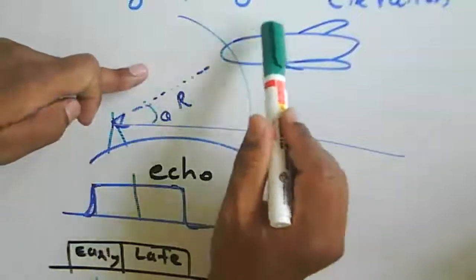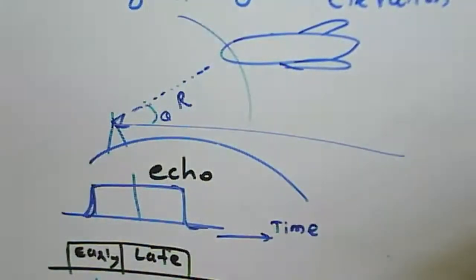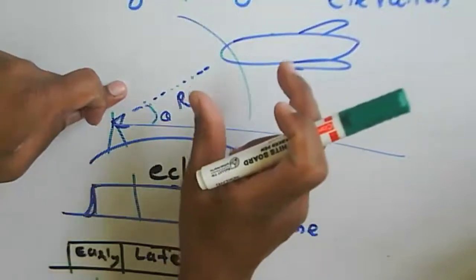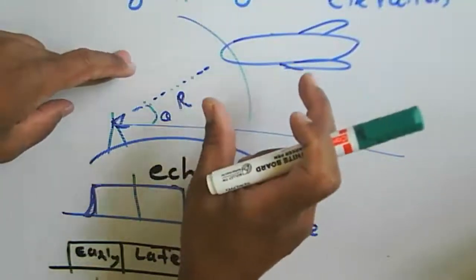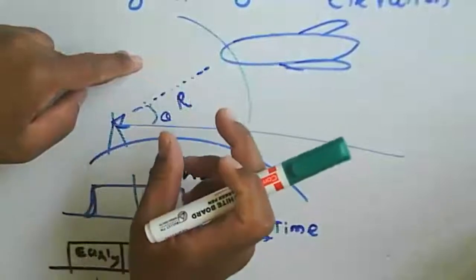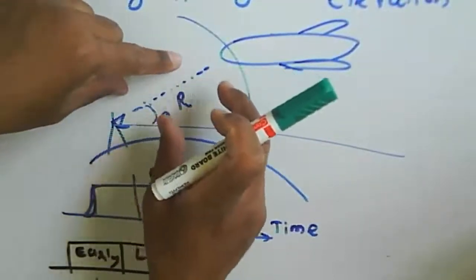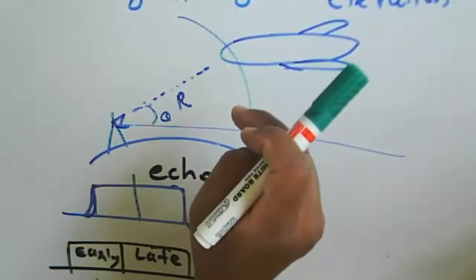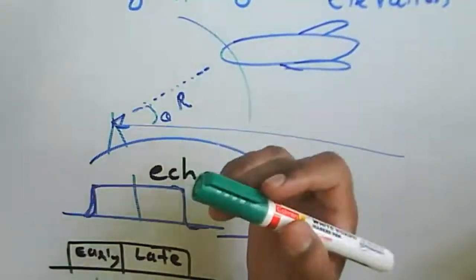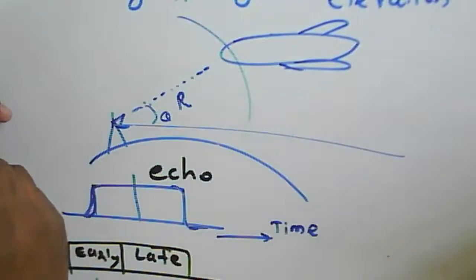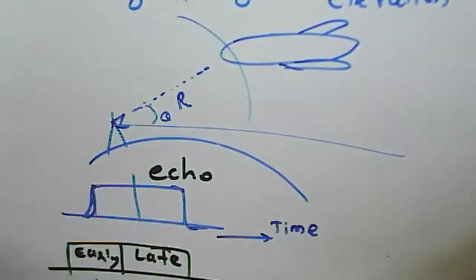Sometimes a target is moving, so there may be a small variation in the angle. While tracking the target, noise may be introduced by the target or by the signal. So the range may vary because of the noise, and the angle we are measuring may fluctuate. In that case, it is difficult to find out the range as well as the angle. That's why we need to use automatic tracking instead of manual tracking.